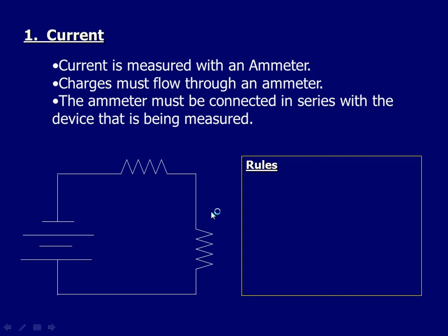Yes. All right, good. Notice, that machine has to be in line with the path because it's literally counting everybody coming in. So, when we want to put an ammeter in a circuit, I've got to get it in the line of the wire. All right? Pay attention. Important part's coming here. Which means I need to cut that wire so I can connect it in line.